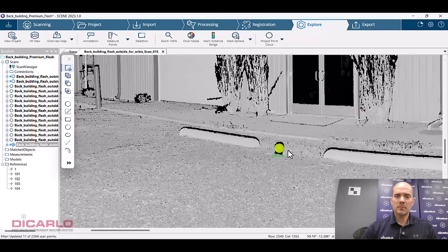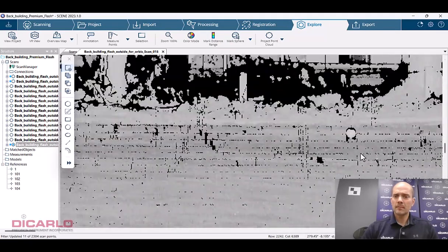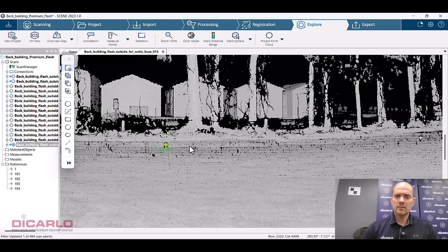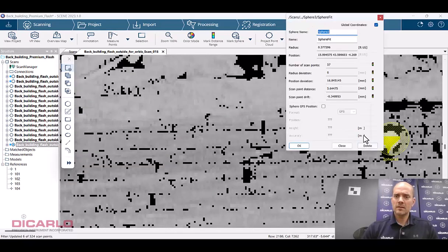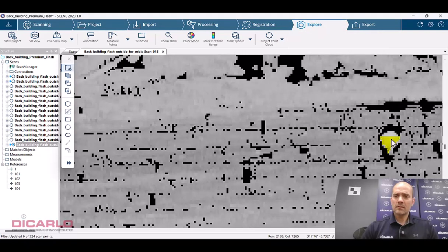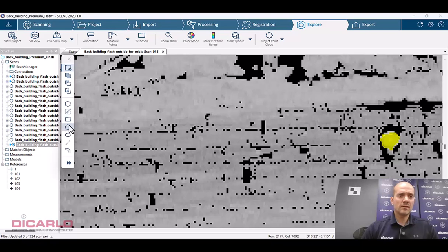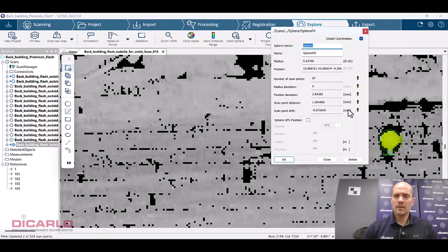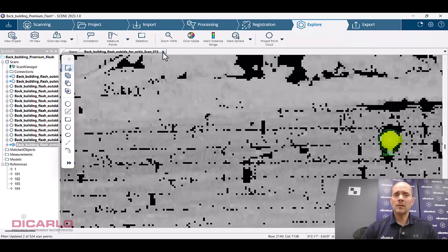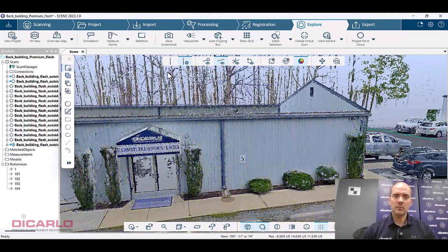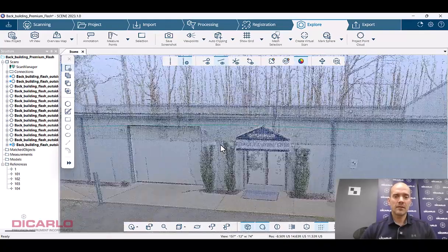All right, we got 700 points on this guy. Let's go here. Nice, 103 points on this, and we might be able to get this guy. Wrong radius, that's the other thing, but let's try elsewhere. 75 points. All right, you know what? Let's try if we can get a better fit by actually highlighting what we want. Hey, better, 87 points. Okay, so that should be enough because I only had 3 targets there plus the checkerboard target, but I'm not concerned about the checkerboard target because I'm really only using the spheres to rotate this in.